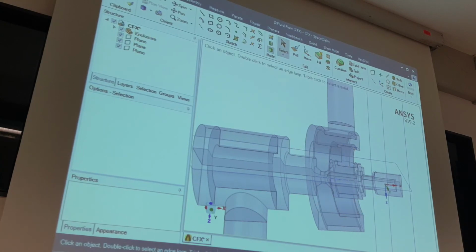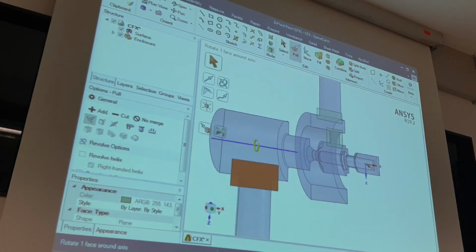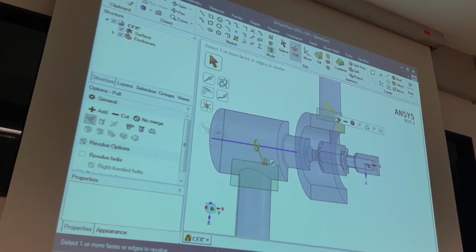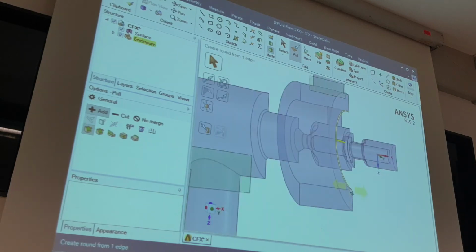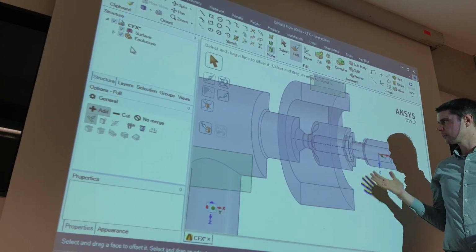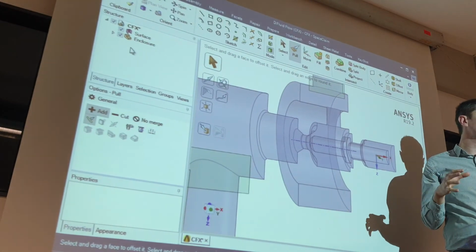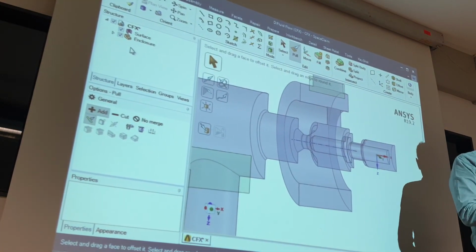For example, if in your examination you draw only this one, the house, or something, you only divide this part, and you create hexamesh. Do you understand? You need to think about what you have to do to have this situation: inlet, outlet, one direction.